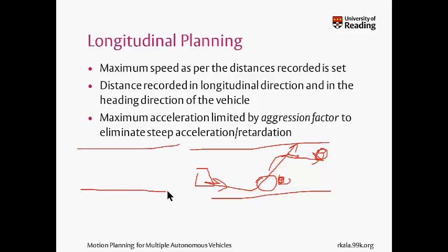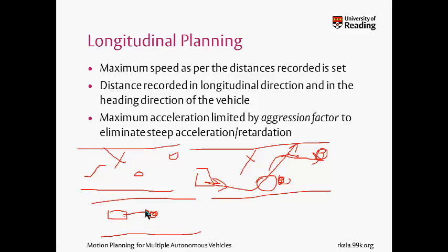On the other hand, if I take a very small speed, what will happen out here is that I will go very slowly and slowly and slowly. So this is bad because I take a lot of time, and that is bad because there is a lot of speed. So I need to adjust my speed accordingly, and the speed principle is very simple. At any time, see where the nearest obstacle ahead is, which I was already computing, and this distance can be converted into the maximum possible speed that I have.